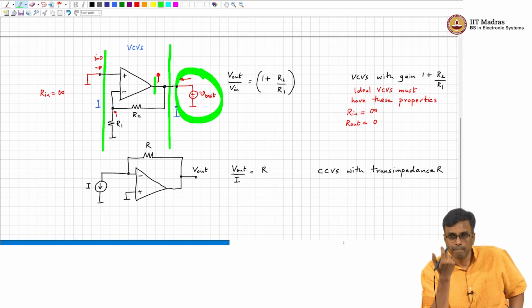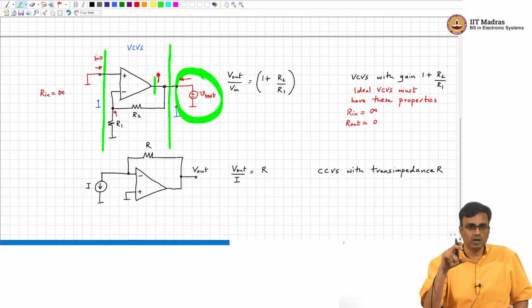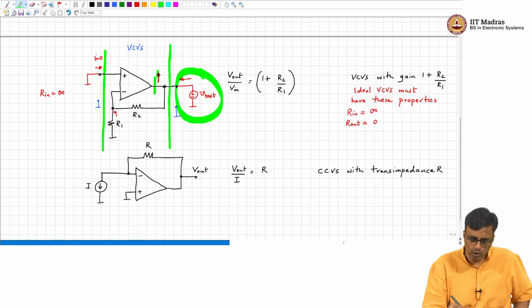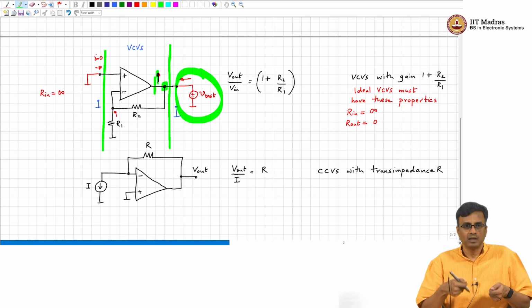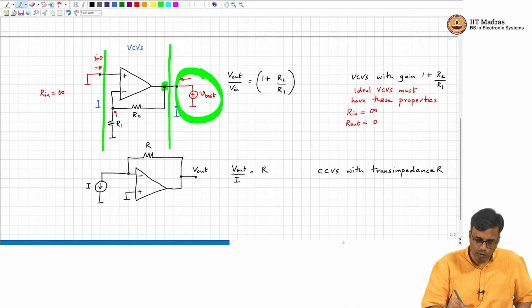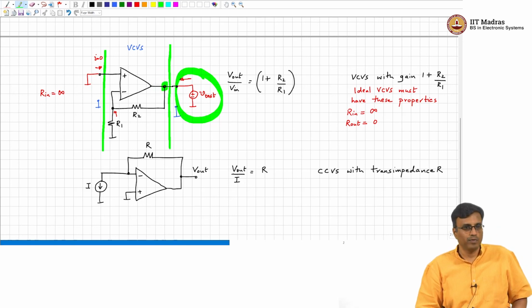It will not increase because we have put a constant voltage there. So, essentially we have broken the feedback loop. You understand, right? Because whatever you do here, this is not changing because you are holding this constant using the test voltage source. So, basically there is no feedback loop when you put the test voltage source.